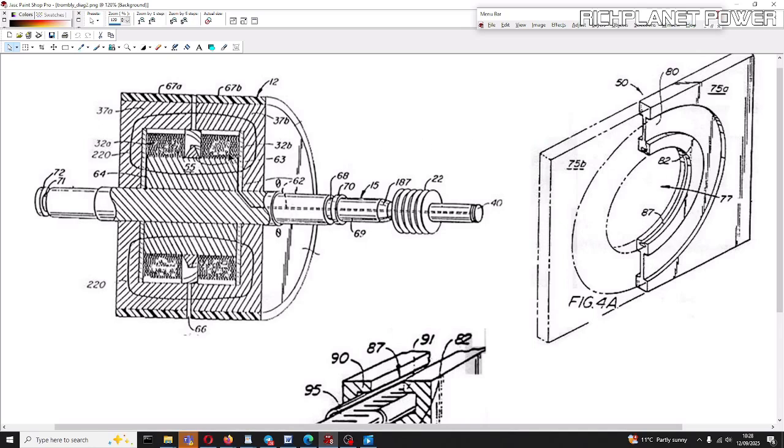And the purpose of this is that you will get the north pole here, the magnetic field comes out of the magnet, it goes around this magnetic circuit, which is iron, and then it comes back into that magnet, and then you've got another circuit there. Now the purpose of this iron is to try and keep this magnetic field as high as possible by encasing it in a highly permeable magnetic material such that the field strength is as strong as possible going through that steel disc.